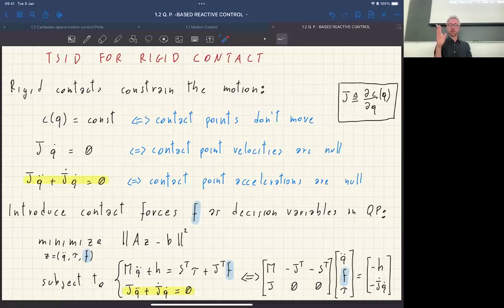So contacts, of course, could be of different kinds. You could have soft contacts, or you could have rigid contacts. In reality, all contacts are soft. Even when you're making contact with a piece of steel, it's still soft. So it means that you can have some deformation of the material. But for modeling, when a contact is sufficiently stiff, we actually assume that it is infinitely rigid, so that there is no deformation at all, because that makes the modeling actually much easier from a numerical viewpoint.